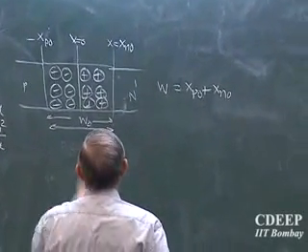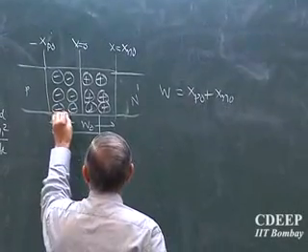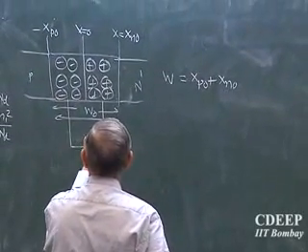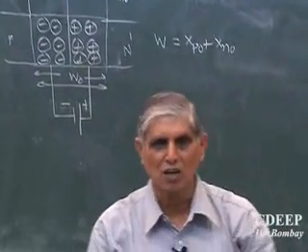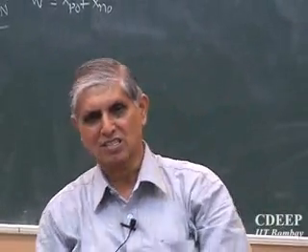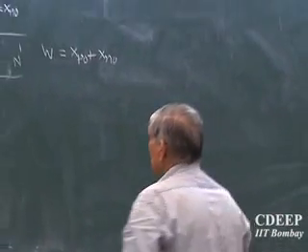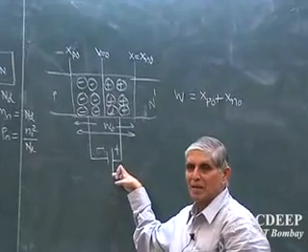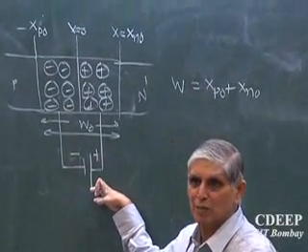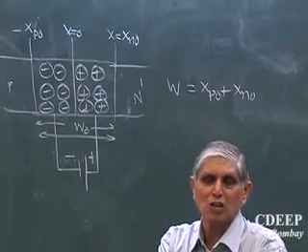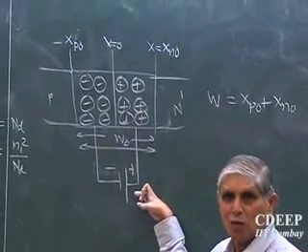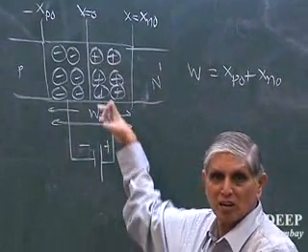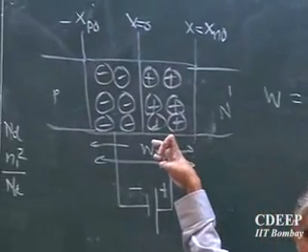Now if that is so, this depletion layer looks as if, I'll rub this out to just show you, this is a positive contact and this is a negative contact. This will be maintained, because if for some reason they recombine, which they cannot, then holes and electrons will again come from both sides and keep this constant. So this depletion region is giving me the equivalent of a battery here. A battery has ionized charge, that's what a battery essentially means. Whatever electrolyte is ionized, that's why you call it a battery. This is a battery here. Why is it created? Because ionized acceptors and donors appear when free electrons leave them.